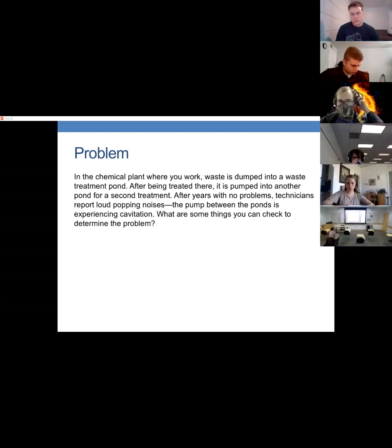Let's try someone like Johnny Pershing. Hey there. Hi there, Professor. What's something that might be happening here, do you think? Okay, well, if cavitation is occurring after a long period of time, maybe there's some buildup in our pipes that is causing some pressure loss that we didn't account for. Yeah, some buildup in the pipe, maybe. So a clog or something causing a pressure loss, or what about corrosion of the pipe? That could do it.